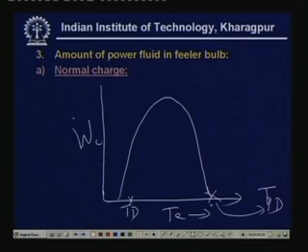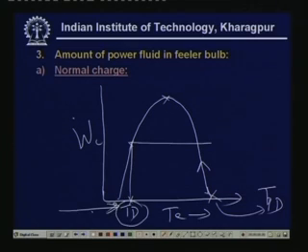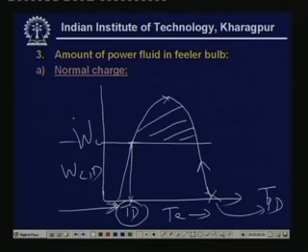So if you remember, if you are operating the system like this, the power requirement first increases sharply like this, right, and it reaches a peak, then it comes down, okay, and finally comes to the design point, right. That means if you have selected a motor which will operate satisfactorily at the design point, that means if your motor gives only this much power, design power, then you find that during this portion the motor is overloaded, right. So this is what is known as motor overloaded during the pull down time.